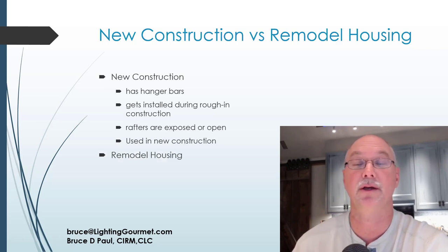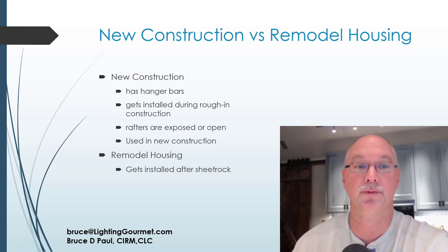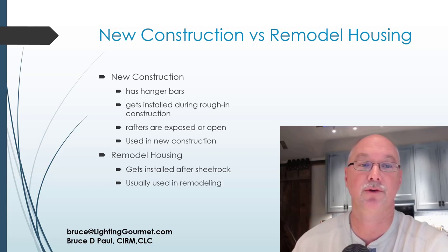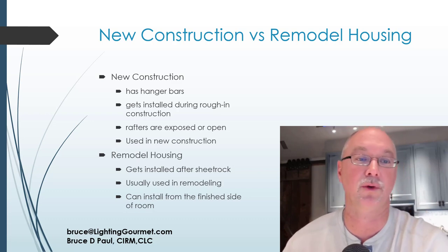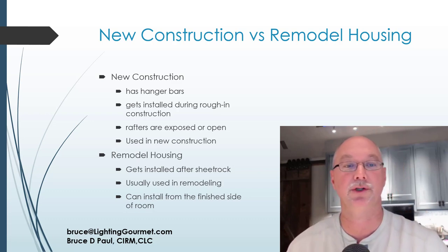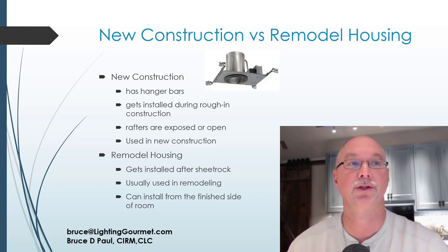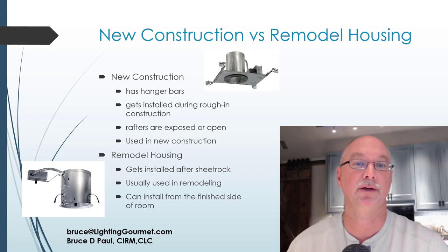A new construction housing is used during new construction versus remodel housings are usually used during remodeling, because a lot of times the sheetrock's left in place. When it is, you cut a hole, you insert the remodel can, and you're ready to go for the most part. So new construction for new cans, and then remodel housings for when you're remodeling, and basically where the sheetrock's left in place. So this is a picture of a new construction. You can see one example with the hanger bars, another example of a remodel housing down here in the lower left, where it basically is held by the sheetrock itself.